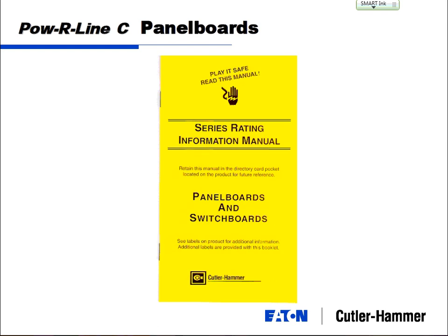Every panel board that's series rated, we do put in this series rating manual, and the series rating manual is always going to tell you the combination of breaker, feeder breaker, and main breaker to give you your series rating.